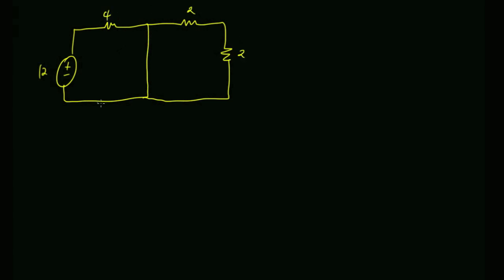Now, did my light get brighter or darker? It's off, right? All my current, once it gets to here, that's it. Show's over. There's no current going through this resistor. Because this is now, what voltage is this? What voltage is this? 0. What voltage is this? 0. See how they're connected with the wire? 0.